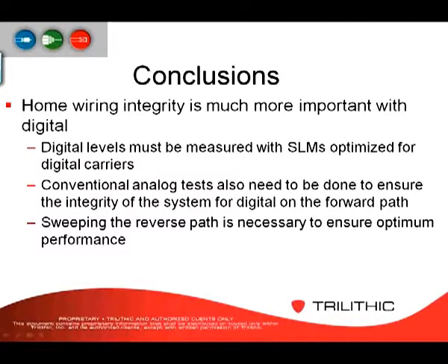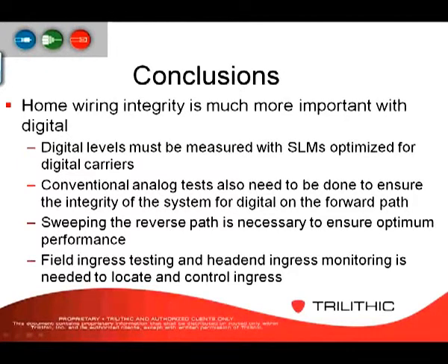Sweeping the reverse path is necessary to ensure the optimum performance. The thing is that return is an area where a lot of distortion will gather. So you want to make sure that that return stays nice and clean. If you can keep that clean, you'll also notice improvements on your forward. Field ingress testing and head-end ingress monitoring is definitely needed to locate and control ingress, because you want to be able to identify problems before the customer has to call. Remember, you want to be proactive, not reactive.